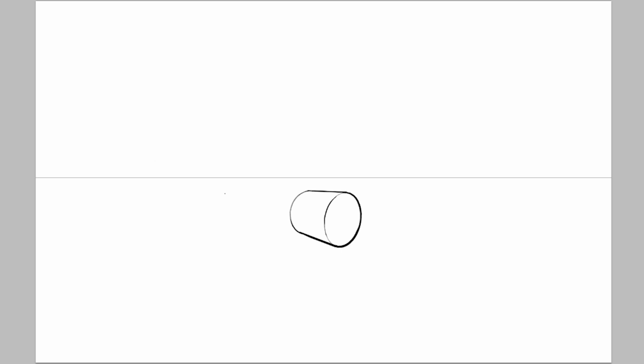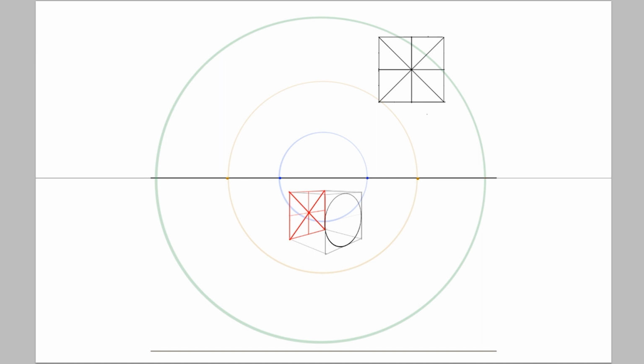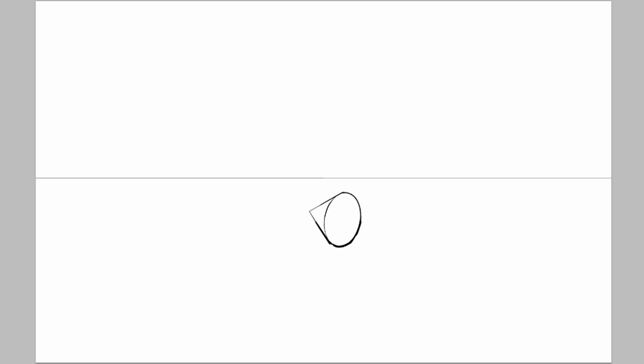Luckily for us, the next construction is going to be quite a simple one, as the cone starts very much exactly like the cylinder. So the first half of the cylinder construction is going to equally apply to the cone. The only thing that is different is that instead of plotting the second ellipse, we are going to draw lines straight down to that central point on the far plane. We can do this because a cone is basically just a cylinder with a squashed top. After that, we can erase our box and finally erase all of the lines for that finish.